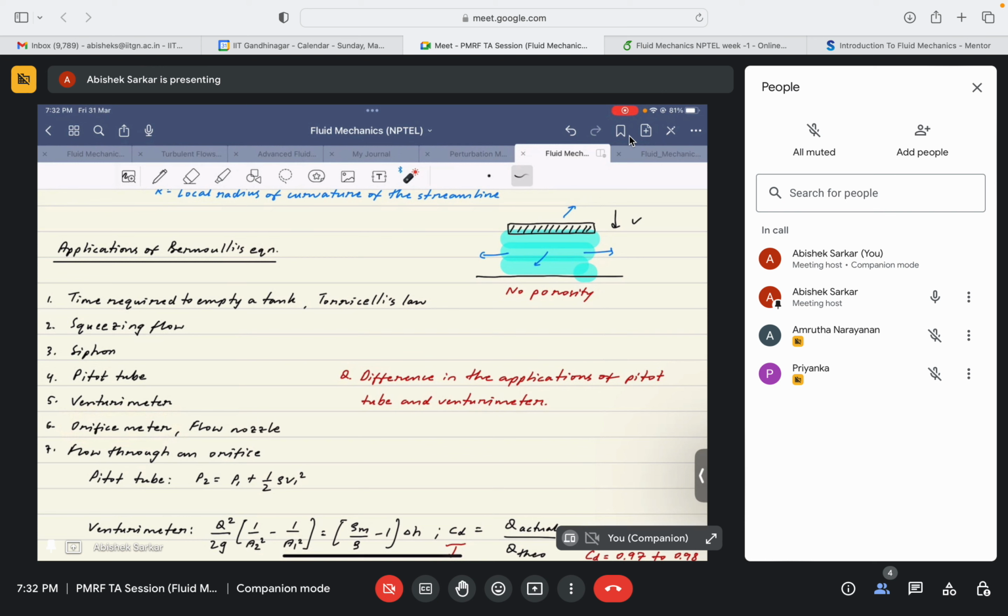But we cannot obtain both of them in the orifice meter, so if we gain something we have to lose something. If we can produce the orifice meter in a cheap manner, at low cost, then we have to sacrifice the accuracy. So that's right.